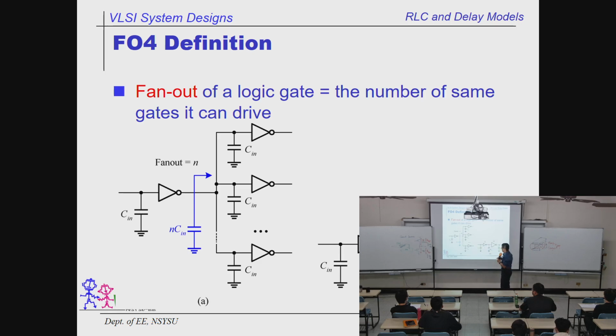Basically, we're going to deliver a signal from inside to the external world this way: 1 time, 4 times, 16 times. Remember the sizing I asked you to do in the first or maybe the second homework assignment, increasing by 3 times, something like that. Similarly, this is the input, and this is the unit buffer. They will enlarge the number by 4 times, and 16 times all the way up.